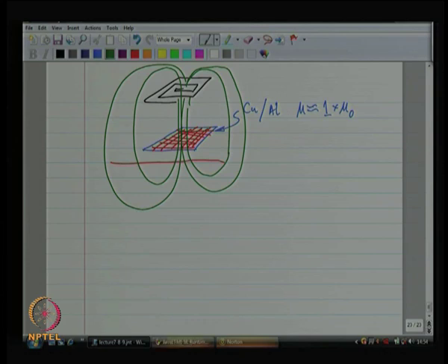Now, you have created a new plate closer by. Now, if this new plate is also grounded, then you have actually increased the parasitic capacitance of this. If the new plate is not grounded, then you have other reasons of concern. Okay. You are going to get a lot of different mutual capacitances, which I am not very sure of what to do with.